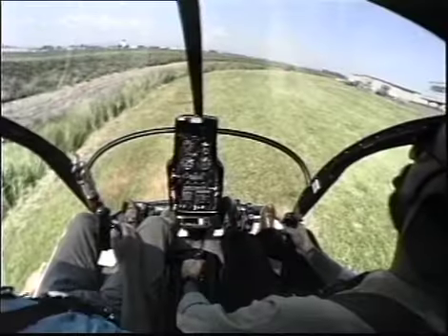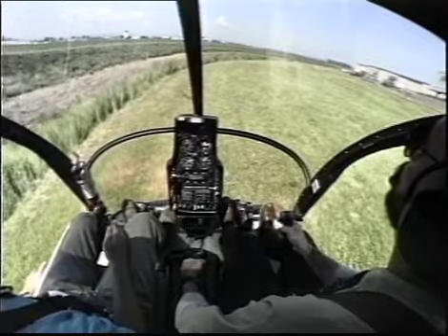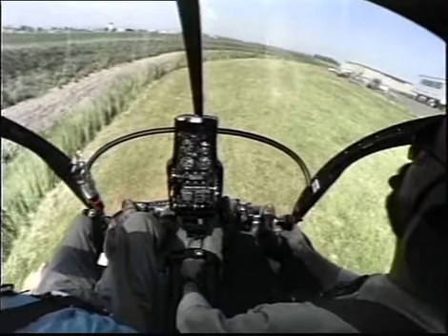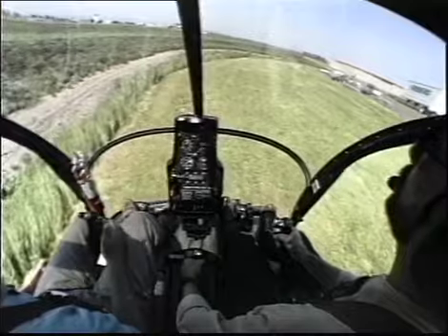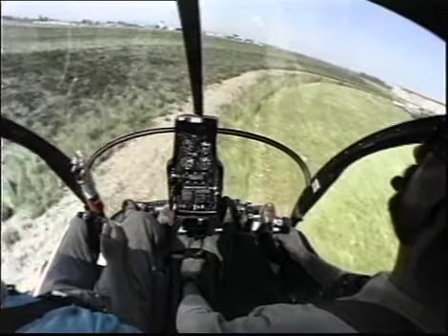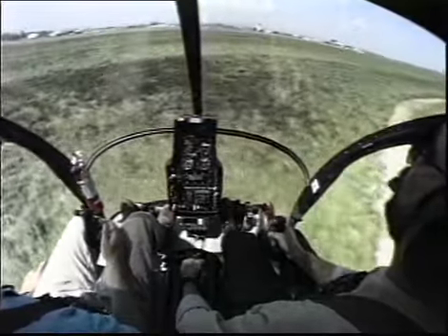Pushed further, and the rotor hub will begin to hit the rotor mast, a hazard called mast bumping or droop stop pounding. A telltale vibration informs the pilot that the aircraft has exceeded its slope capability. Abort immediately and select a new, less steep landing site.